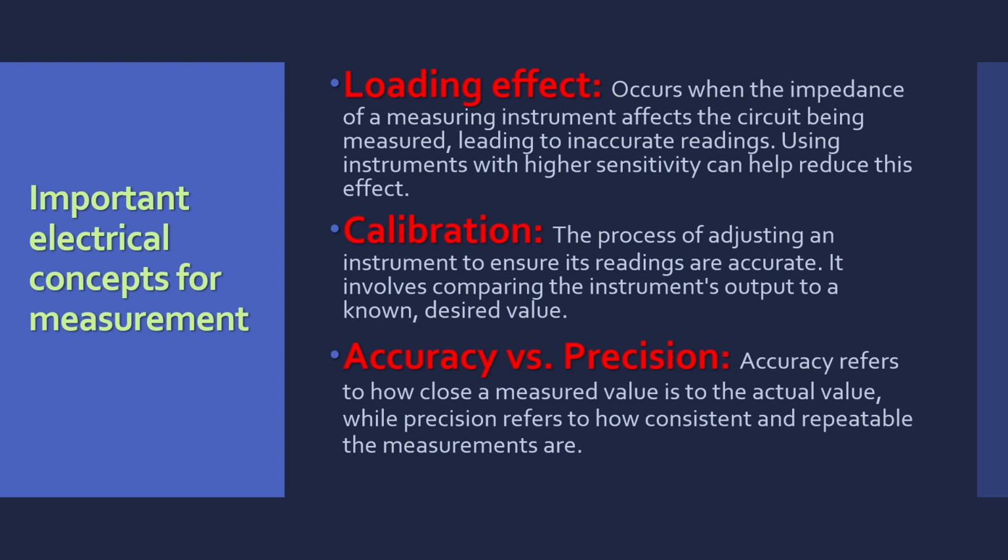Then some important electrical concepts for the measurement are essential to know. First is loading effect. So what is loading effect? It occurs when the impedance of the measuring instrument affects the circuit being measured.